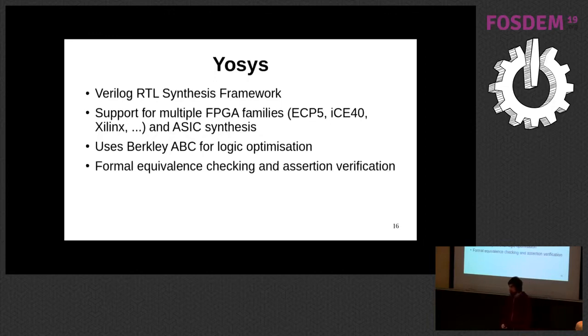So, as well as synthesis, it can also do formal equivalence checking. It can do assertion-based formal verification, which is something that, as far as I know, there is very little else out there in the open source world. And this can be a very, very powerful way to verify designs. And it's got all kinds of other really obscure things. I think it's got a SPICE backend that can do simple simulations, it can do transformations, all sorts.